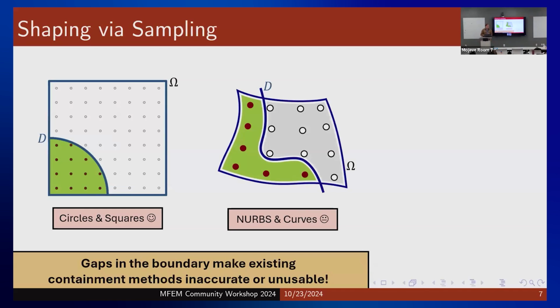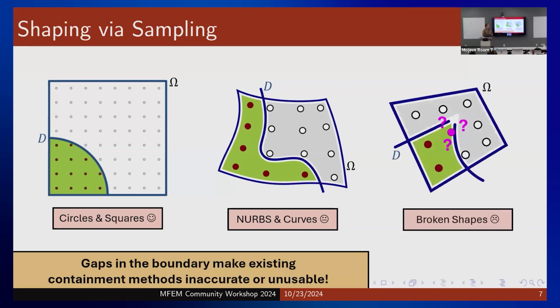But at the same time, there is a separate but just as impactful issue dealing with watertightness, which is when you have a shape that doesn't technically, rigorously have a volumetric interior to actually query. It sounds counterintuitive, but it happens all of the time in practical applications because all it takes is for a single pair of edges to not connect perfectly like they should, and it can cause your otherwise fairly expensive and complex shaping procedure to just crash, sometimes completely unexpectedly.